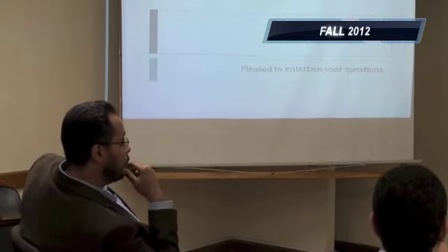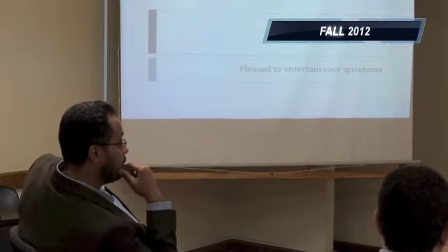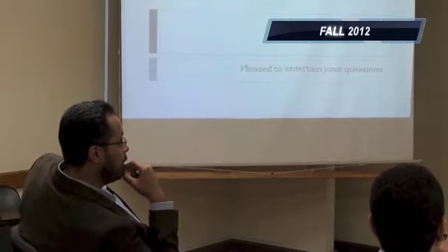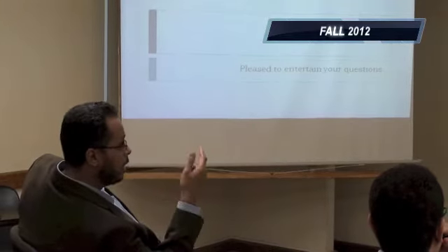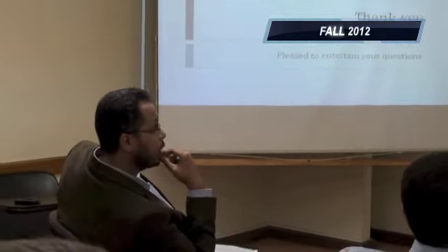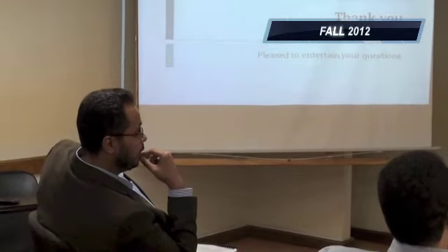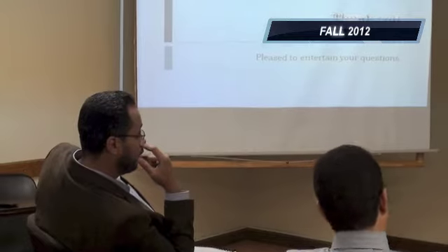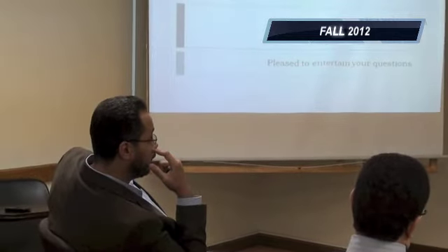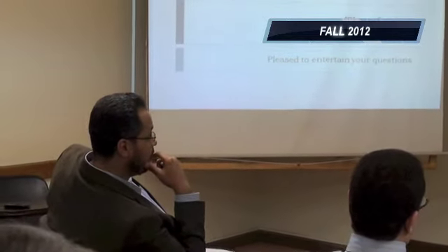For the other group, they had 2 pylons, so this is very significant. For you, you have 1 pylon only, so the implication of multiple support excitation could be different in the analysis. So if you're going to include the seismic, at least conceptually address the effect of this element.